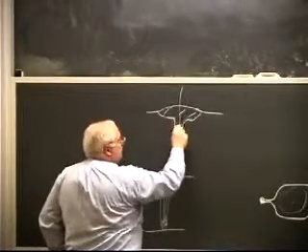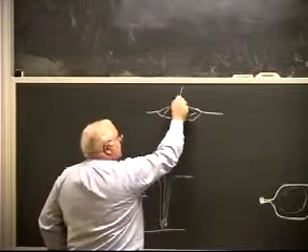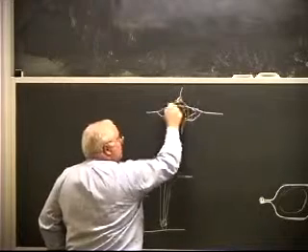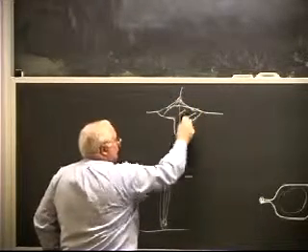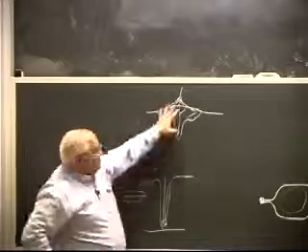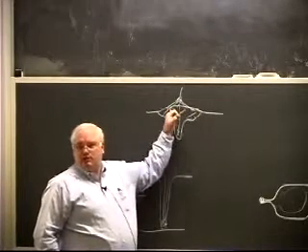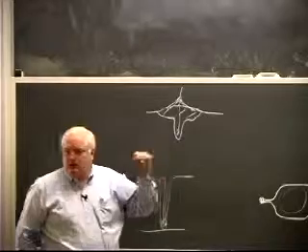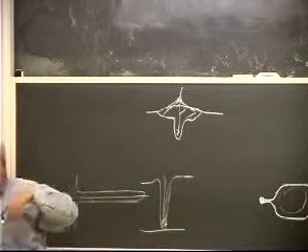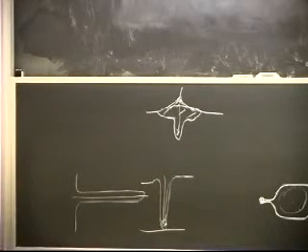You've got your beam coming in, drilling a hole, but you've got some defocusing going on up here in the plasma, which spreads the beam out and gives you low heat intensity. So I really have two weld pools: a shallow weld pool, which is the head of the nail, and a deep penetrating weld pool. Depending on how you set up your beam parameters, you can get the nail head shape, and that's more common in lasers because the photons are more readily absorbed.